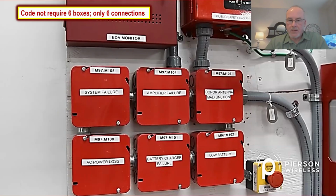It only requires 6 connections. So there are various ways to do this, but this just illustrates how this works. Now, down here at the bottom right, under that logo, you can see a kill switch, a power kill switch. That is not required by the code. It's optional. It depends on the AHJ. Down here in the Charleston, South Carolina area, according to the guys that I work with, the local integrator partners, they don't require that. They haven't seen that required here, but it may be different in your jurisdiction, in your area.